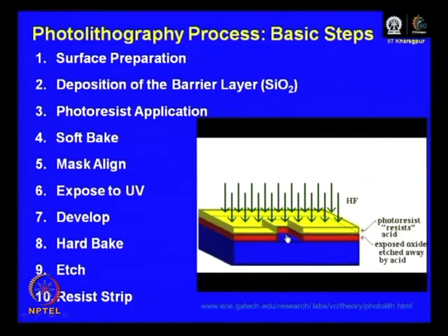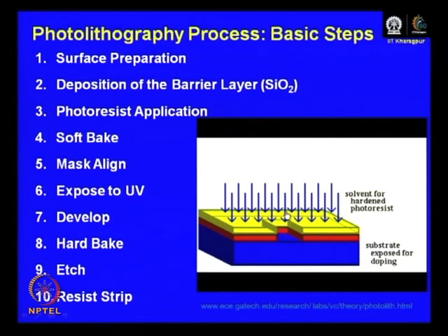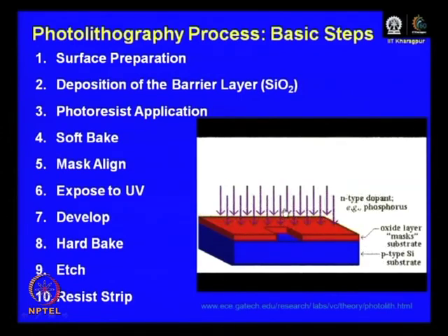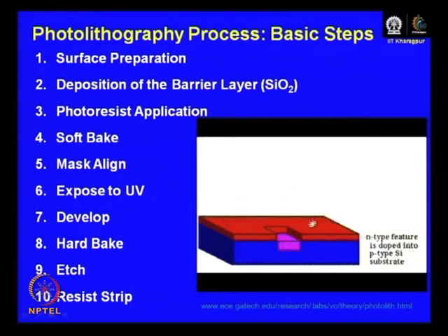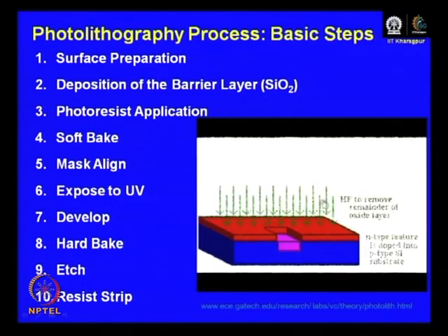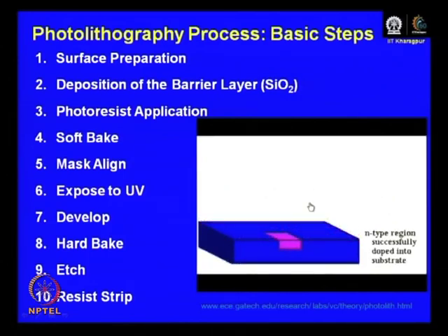acid, and then if the photoresist layer remains present during the diffusion reaction, the polymer layer might get contaminated, and some chemicals from the photoresist layer might also react with the surface, because it is a liquid state reaction of the photoresist layer as well before your doping reaction starts. So, that is precisely what is done. The photoresist layer is also removed, and then you do the doping reaction, and finally you get rid of your oxide layer itself. Of course, for all practical purposes, this is followed by another process of metallization.